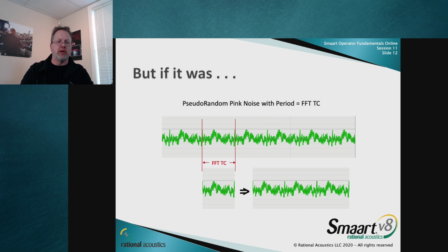When it says sync noise, it's not synchronized to start and stop when you begin and end your measurement. It's the size of the noise repeat that is synchronized to be the same size as the FFT, because when we're doing transfer function measurements, we're running continuous overlap measurements. So we're not synchronizing start and stop of our noise. It's just the size of the noise.